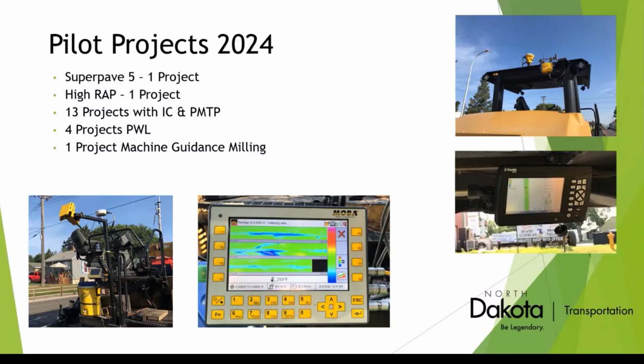So very interesting job. Whoever gets that, or if you're familiar with that, I would say that might be the lead. And LiDAR is just a radar basis, and I think you'll probably see that in a lot of airports do that now, use LiDAR on pavers. And again, I think a lot of the high-speed racetracks, when you pave them, they're using LiDAR guidance to do crown and slope control, not an extended reference on the paver itself. So the two match hand in hand, and so this is a great start.